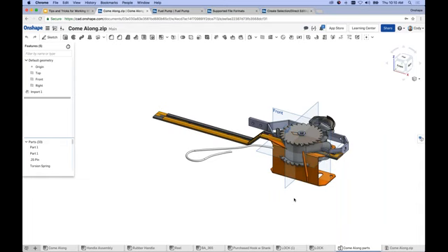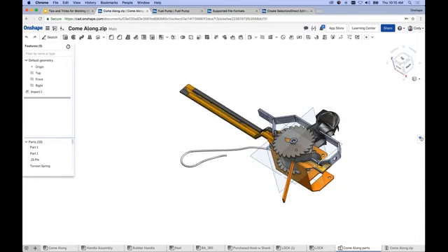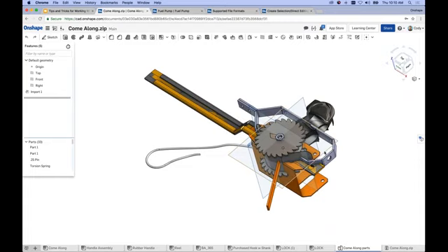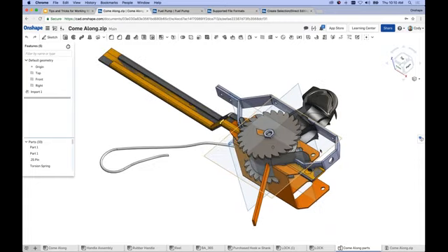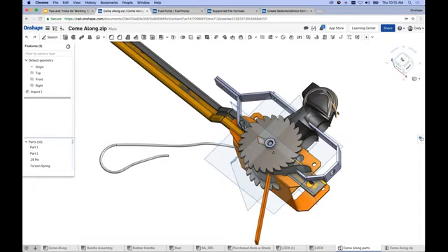But it's important to stress, one of the first things I would stress about imported geometry is it comes in the orientation it was originally modeled, right? And so all of your imported parts will appear in one part studio, and in essence, all brought together. In this case, they were all modeled with respect to this origin, right, in this position.